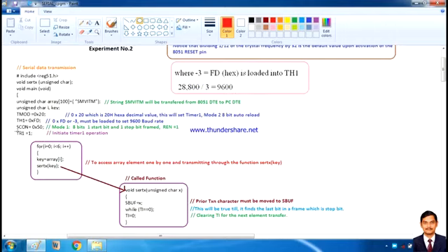Next, SCON. SCON is serial control. Since we are using serial communication, I have to set this 8-bit special function register. As we already discussed in the previous video, this is mode 1 serial communication, which is 8-bit, with 1 start bit and 1 stop bit framed. A total of 10 bits of data communication happens, and this bit must be 1 in serial communication. This is the receiver enable. In order to initiate the timer operation, we have to make TR1 equal to 1, so initiating the timer 1 operation.